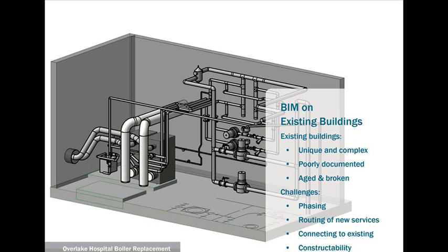some challenges that existing buildings come up with that's unique from new construction is they're occupied. You need to make sure that the contractor can get into the building, do the work, and get out without disturbing all the people inside of the building. You need to make sure that you disclose the arena that the contractor gets to play in when you submit the documents so they can be properly bid.